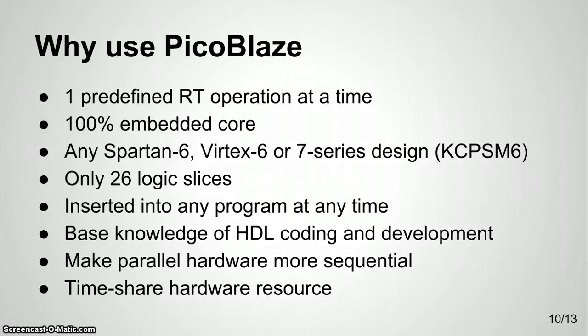There is no need to plan ahead if you should or should not use it, as it can be inserted into any program at any time. Skill level required from the programmer is anything in between a skilled hardware programmer to a novice. You only need a base knowledge of HDL coding and development. As to why one should embed a microcontroller into hardware, this is to make some of the parallel hardware more sequential in its execution. It is also used to time-share hardware resources when several slow tasks need to be performed.